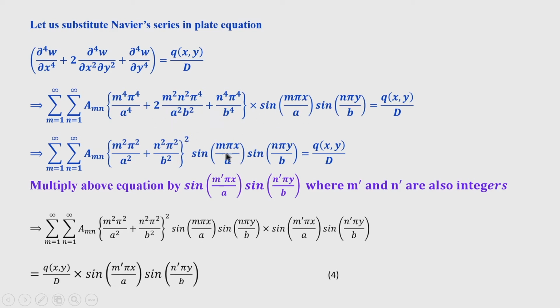Then this function is written here, sin(mπx/a) sin(nπy/b), and the right-hand side is the loading function q(x,y) divided by D. This loading is a distributed loading, that means q is also a continuous function of x and y. Now, multiply both sides of this equation by sin(m'πx/a) sin(n'πy/b), where m' and n' are integers, and m and n are also integers.